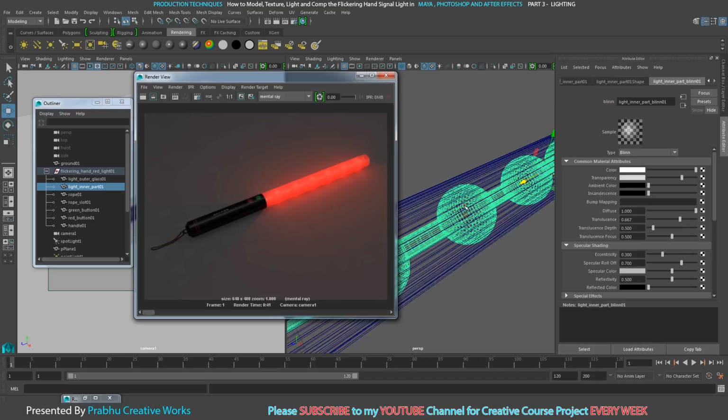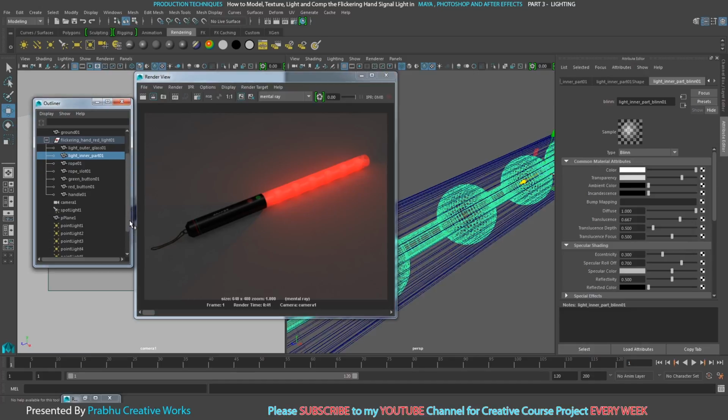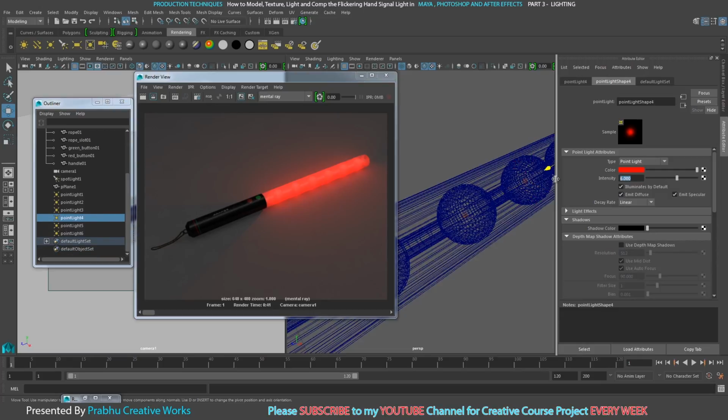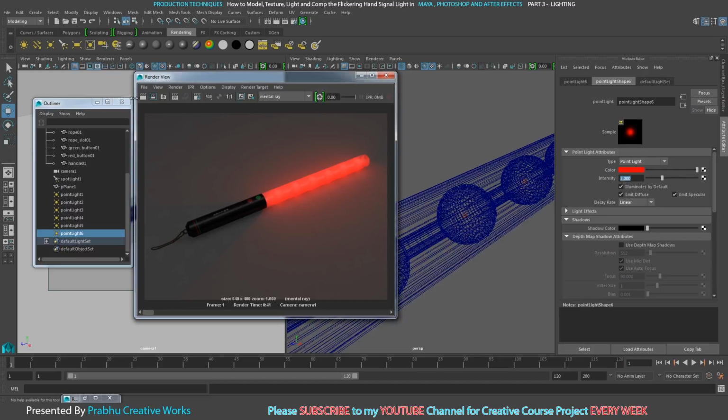So now I want to reduce my point light values. It's too high, I think. So I will select my point light and set the value to 3. Select each and every point light and change it to 3. It's too high, so I will change them to 3. So compare this one and click render.